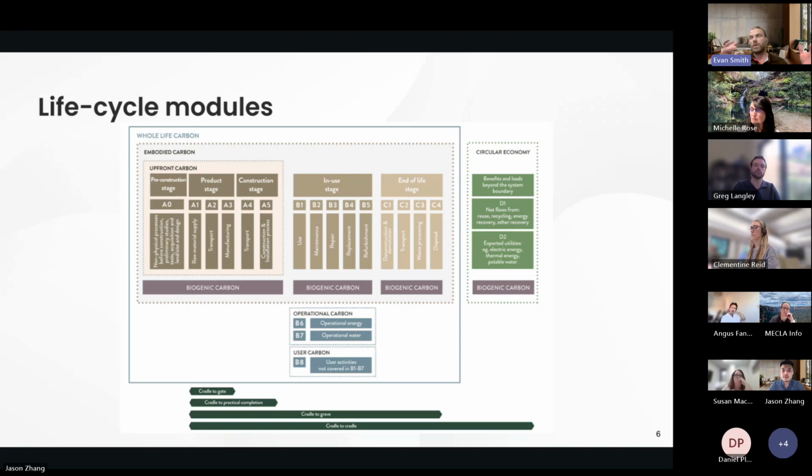So when you want to look at a whole building life cycle assessment, you want to ask, how many times do I have to paint the wall with this product? Okay, there's another product which will last twice as long, but maybe has a slightly higher impact. So you can start looking at those different scenarios: is A better than B if I don't have to paint it as much? You can look at the total life cycle assessment. So I think it's really good that EPDs declare all those various stages so you can compare. Asphalt's another one as well. In use, some might have higher emissions but a longer life, and vice versa.